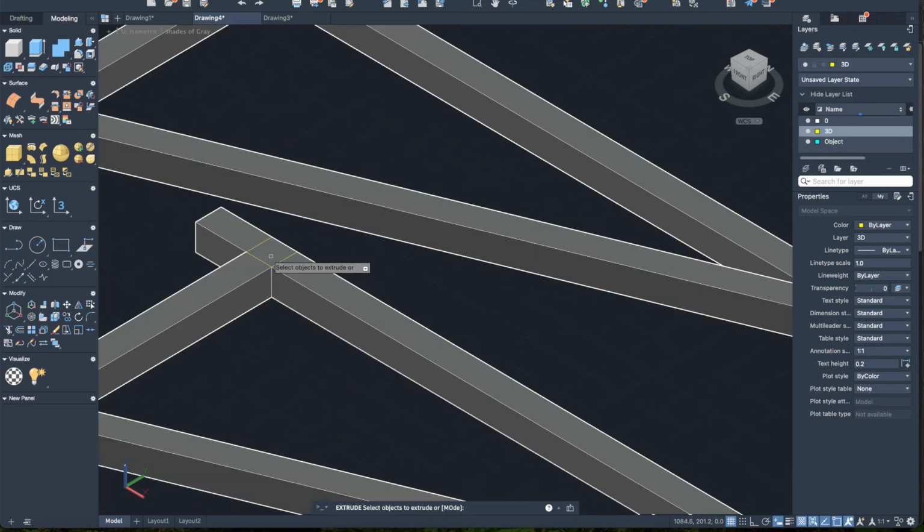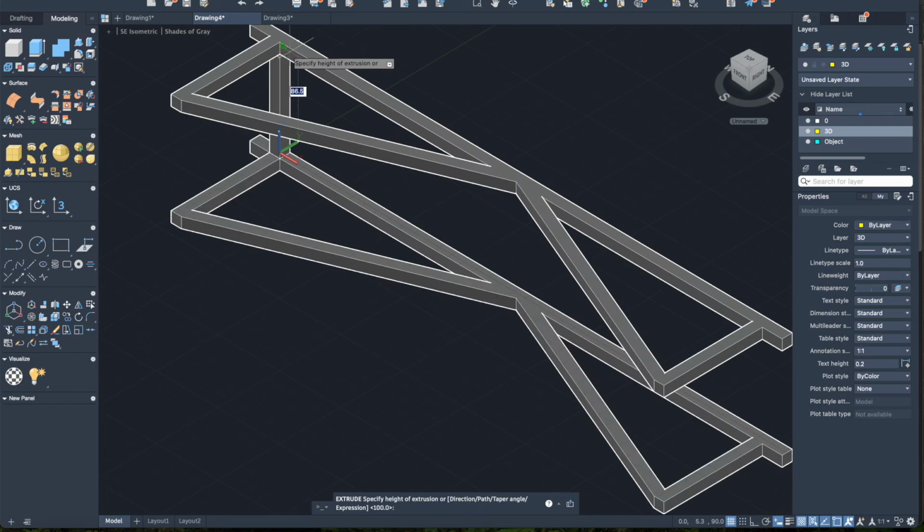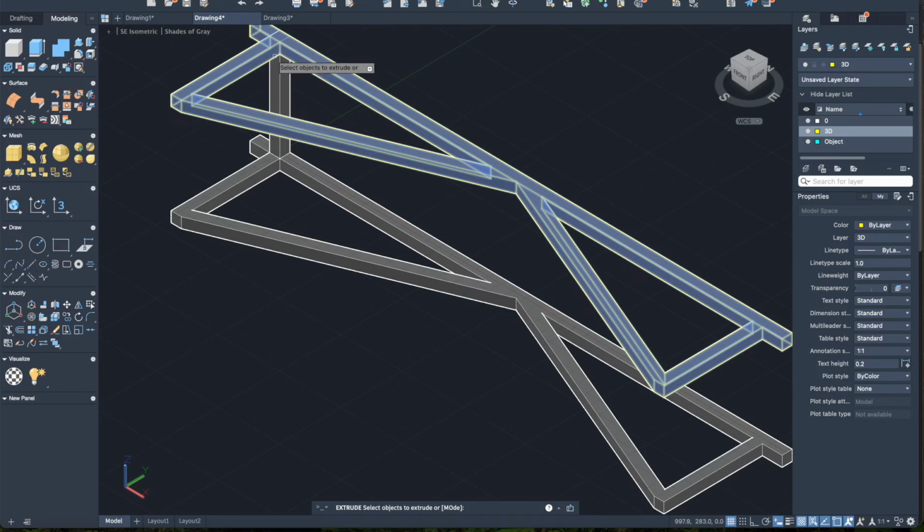Now this is where it gets a little tricky because it wants to grab the other part. Okay, hit enter. Now you can either click it where it connects, it sort of snaps into position, or to be cautious, I just put in 100. That makes it go all the way through. If you'd rather it was seated at the beginning, it would be 90. So let's do that.